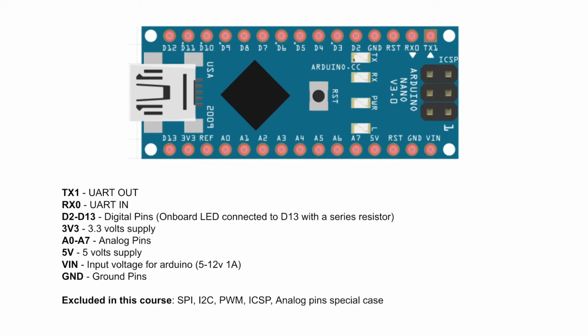So these rectangles, the yellow rectangles with a white rectangle in it, this is an LED. You have 4 LEDs on board on the Arduino Nano board, and these are used as an indication to your processes. The first two are the TX and RX pins. Whenever you are exchanging data with your Arduino board, Nano or UNO, whichever board it is, these two LEDs will blink, showing that the data exchange is taking place.